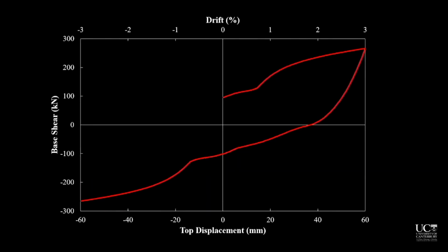So, design provisions. After numerical and experimental studies, in order to come up with the design provisions for prevention of this mode of failure, we did a bunch of numerical studies on walls with different characteristics and investigated the response, the failure modes, and the sensitivity of the model to different parameters. So first of all, let's again see a specific cycle from loading and unloading and the out-of-plane response of walls at large in-plane curvature demands.